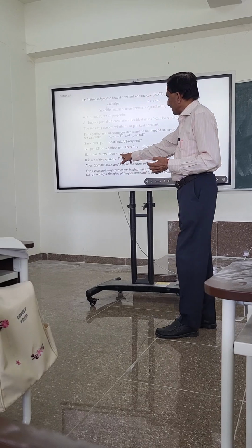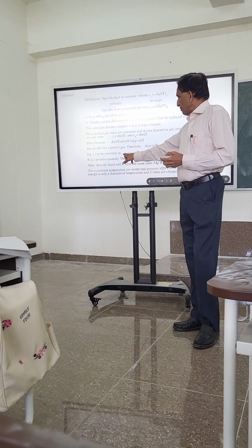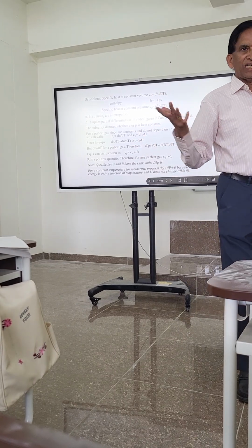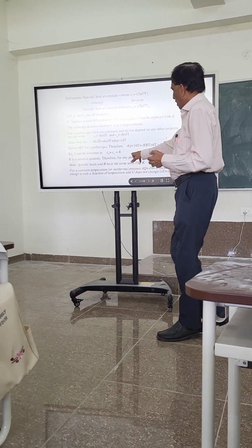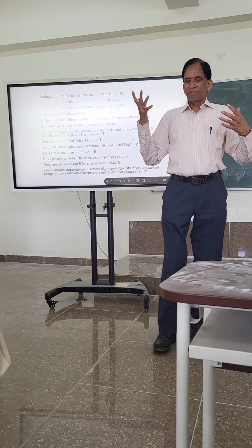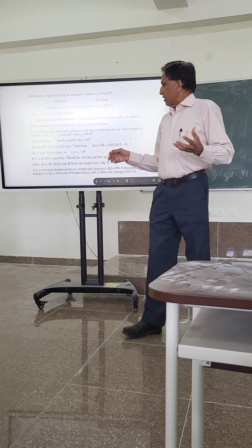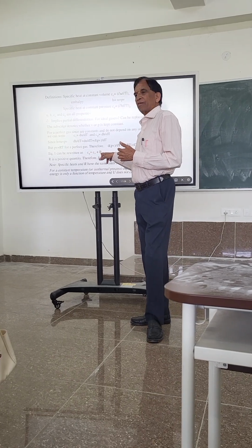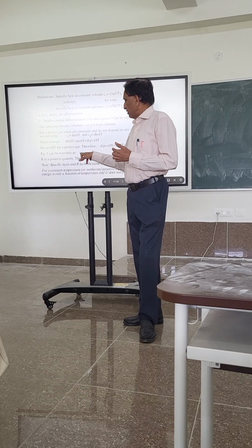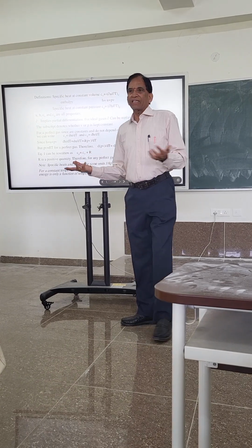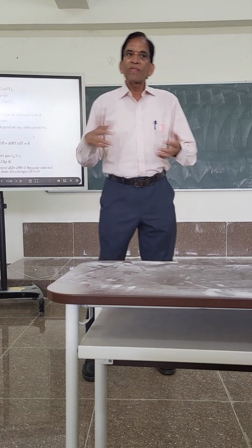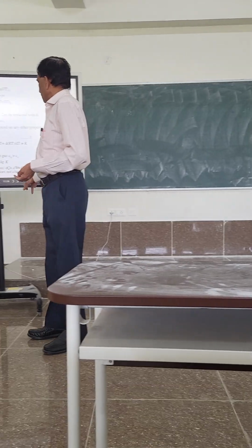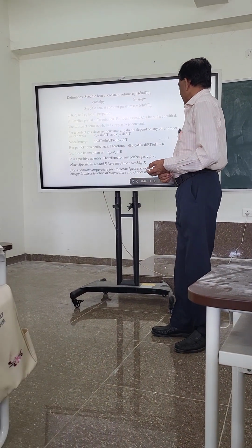Also we saw from this equation that the specific heat at constant pressure is equal to the specific heat at constant volume plus the gas constant. Of course, I left it as R, without putting a bar or anything like that, simply because all of them must be in consistent units. If you are using molar units, this will be the universal gas constant. If you are using mass units, this will be the characteristic gas constant. I left it just floating so that whatever is convenient for you, you can just use that. The units will always be chosen consistently.